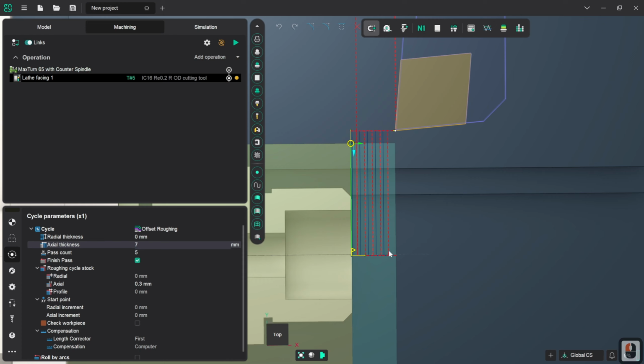So we're now going to click on Generate Toolpath of the current operation, and we can see here how it comes in, takes off the first, retracts, rinse and repeat, which is exactly what we want it to do. However, for the sake of sanity checking, I will always insist on simulating each operation as I've completed it.